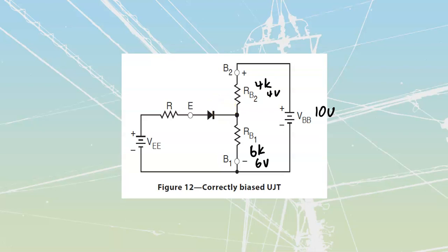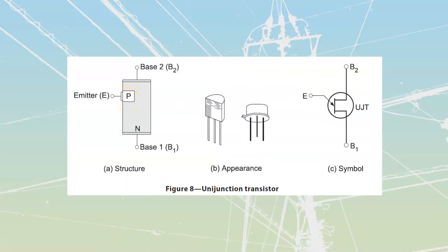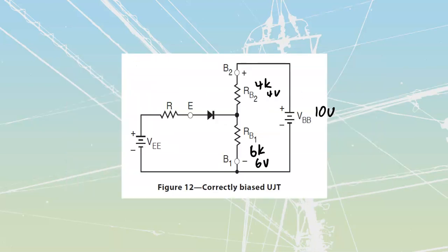Because we have got this thing embedded in a dissimilar block, there is going to be this depletion region around the outside, which means that we have to put that in as well. So it's 0.7 volts, which is what we say is our default for most of these. So that's what this section right over here is going to be, this little diode that they have. The diode is just representative of that barrier potential. And then we see that over here we have got another value of resistance. We can have a variable resistance. We can have a fixed resistance.